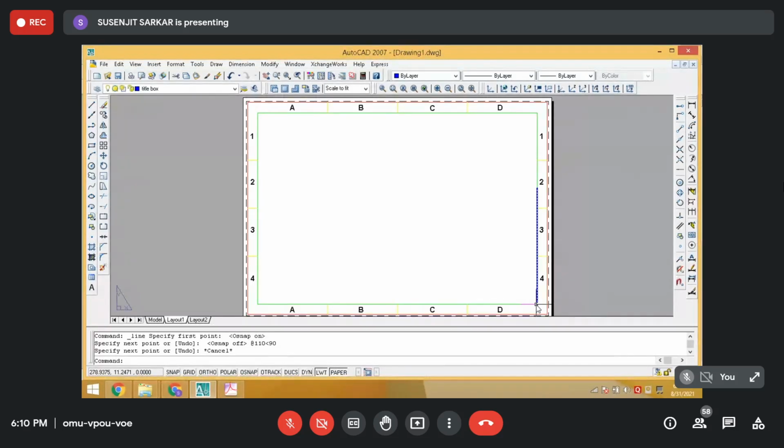But for the second point, while it is coming over here, since by default the snap and tracking is on, it will track the midpoint and this intersection point, all these things. So due to that, the line actually shifts from 90 degrees.